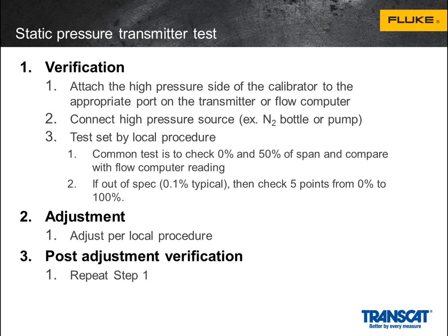It's pretty uncommon to see pressures, especially once you actually get into the pipeline world, low enough that you can actually use a pneumatic pump. And so you'll have to make sure that's set up and attached. Typically what we'll see is that you're going to check 0 and 50% of the span, and you'll basically compare that with the flow computer reading.